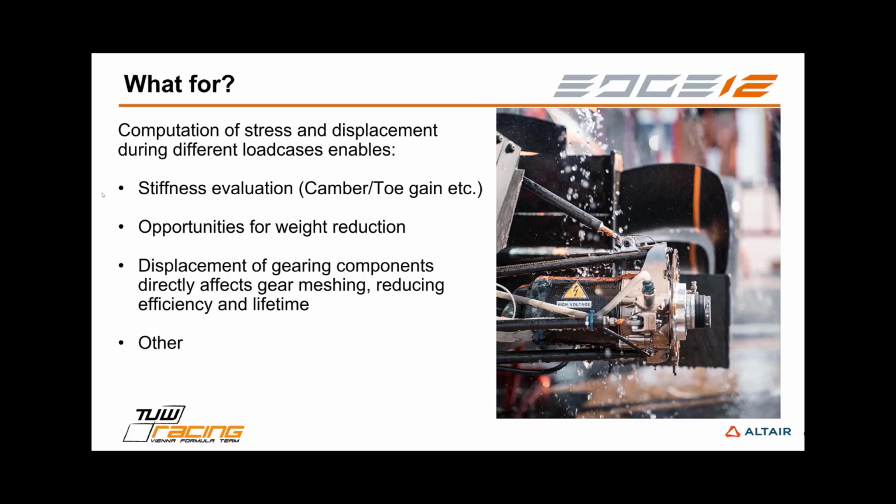So what are we using this simulation for? First of all, we want to make an estimate on how the assembly deforms under load. So we want to make a stiffness evaluation. Secondly, we are always looking for opportunities for weight reduction. And last but not least, the displacement of our gearing components directly affects the gear meshing. So we want to calculate the exact displacement of our gears in order to later on compensate for that.